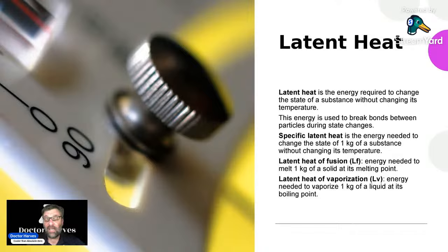Right, so latent heat is possibly a difficult concept to get your head around, but latent heat is the energy required to change the state of a substance without changing its temperature. The reason it doesn't change in temperature is that temperature is a measure of the kinetic energy of the substance. If there's no change in temperature, then the particles aren't moving around faster. The energy is not being used to move the particles around, it's being used to break the bonds between the particles during changes of state, from liquid to gas, or say solid to liquid.